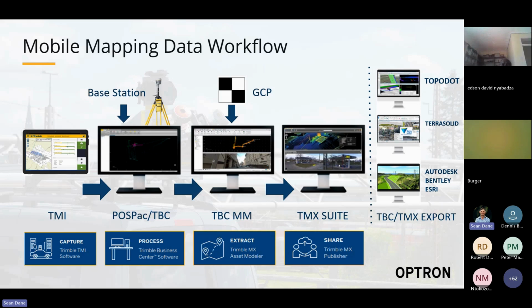Once you've got everything tied down to control and registered, you then have the ability to start to extract features, classify the point clouds, and do the necessary survey work, whether it's extracting center lines of roads and curbs and barriers, doing cross sections, volumes, you name it, you can do it. And if it's more GIS orientated, you can write your data directly, as I've said before, into Esri through geodatabase connections, or export the data into other third-party formats.